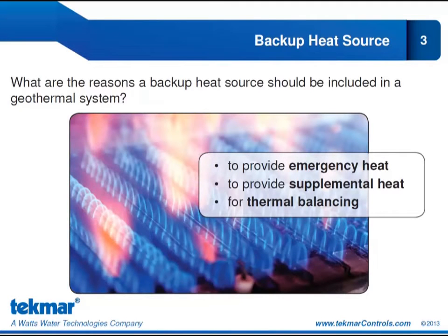The question of thermal balancing relates to our earth loop. So we want to make sure that the amount of heat that we are drawing from the earth is equal to the amount that it can also recover. So it recovers heat from the cooling process when the system is rejecting heat back into the earth, and it can also recover from the sun. So what we want to make sure is that it is balanced year round. We don't want to take more heat away from the earth than can be recovered.